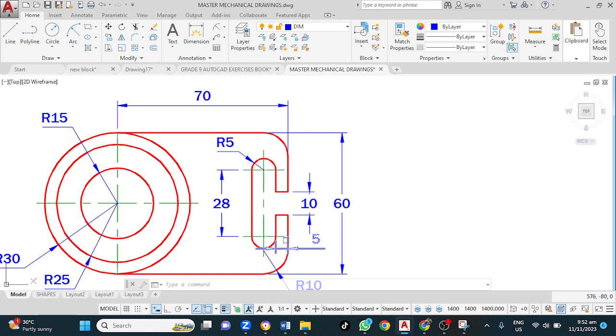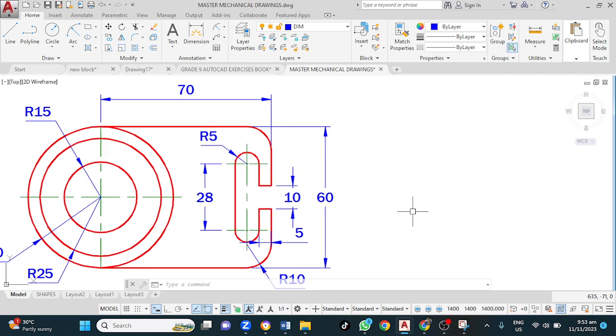and that would be 5 plus 5, 10, from here 10. Then we could use a circle of diameter 28 to get this center, that center. Or we could use a line. We could draw a line here, then use either match, multi-line, or offset, then fillet to get those arcs. Okay, let's get started. This shouldn't take us more than about 7 minutes or so to do.